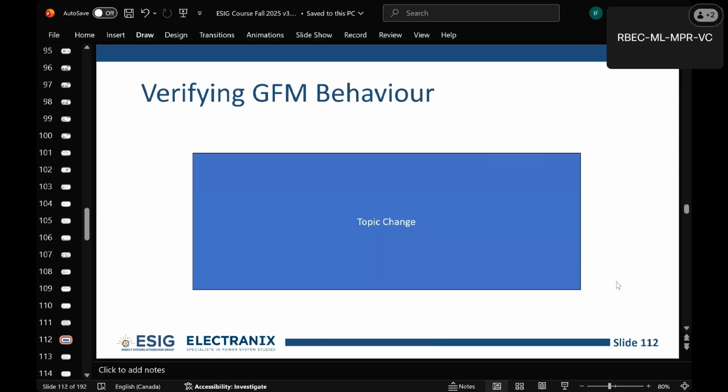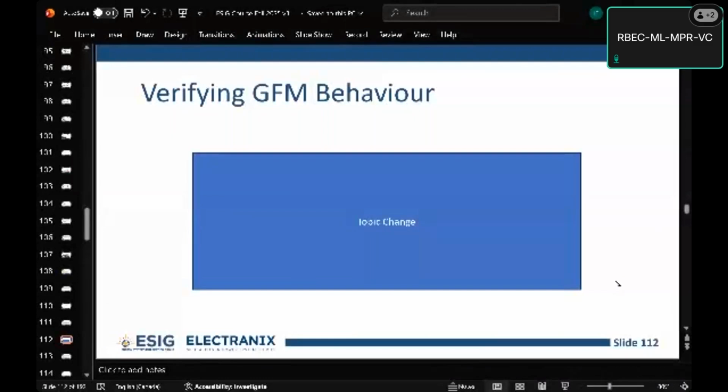The other thing I will say is that we can't break the laws of physics with grid forming. If you're going to go to an SCR of 0.7 in a fully inductive system, you're going to collapse your voltage, and there's nothing the grid forming can do about that. We can't break the basic laws we have for power transfer and angle. Sometimes we get the sense that in a super weak system we can just put a grid forming battery there and it'll solve the transfer problem and voltage collapse we showed. That's not true. If you break that law of max power transfer, your voltage is still going to collapse.